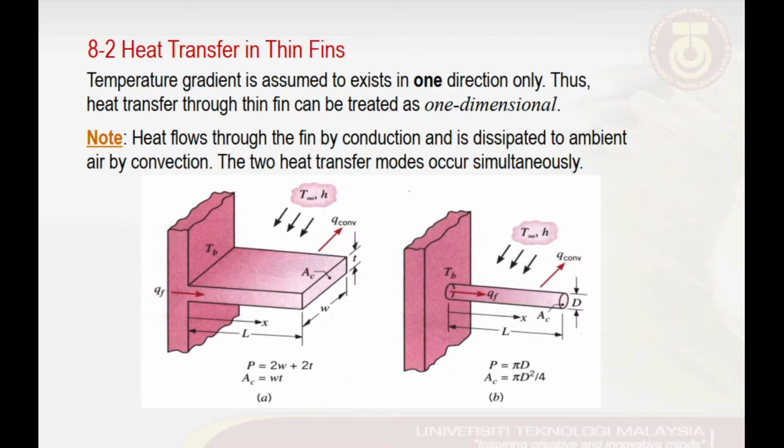We also limit our discussion to one-dimensional heat transfer in this thin fin, where if we consider a single fin as shown in these figures, one-dimensional finite elements will be used to model how much heat will be transferred from the base body, which is located there, into the ambient air.